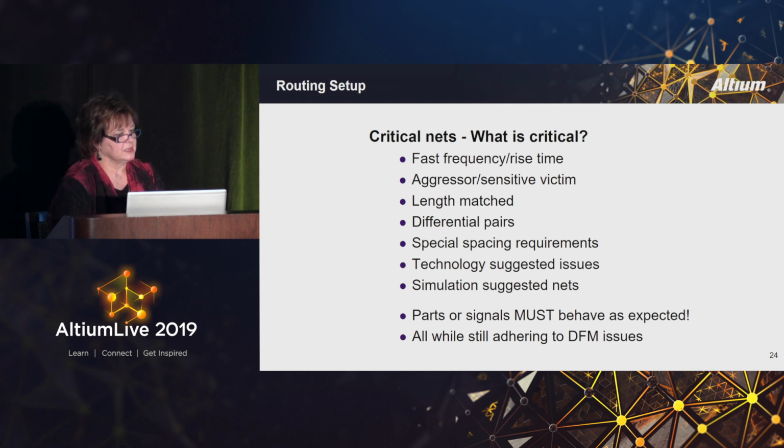Then anything that the technology might suggest, for example, if you have certain buses or certain types of boards that require things to be a certain way, that would be something that you would need to set up as critical. Anything that simulation suggests should be done a certain way would also be critical. Because you have to assume that when you're making the board, all the parts and signals must behave as expected. So it's not going to happen unless you make it so.